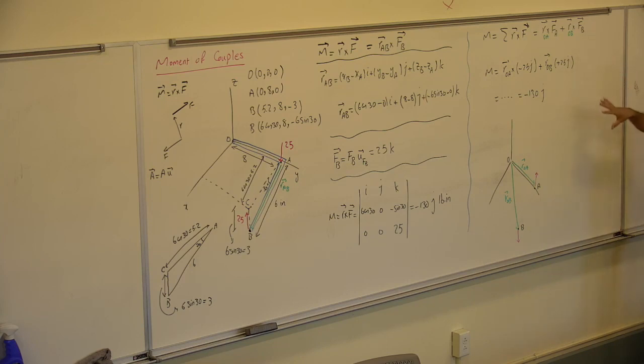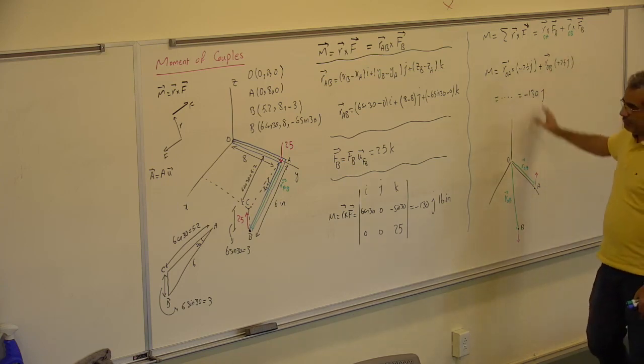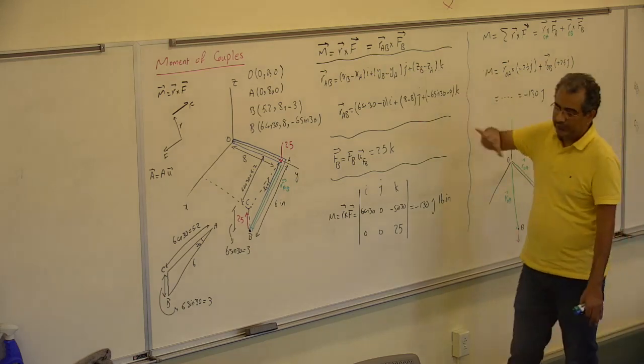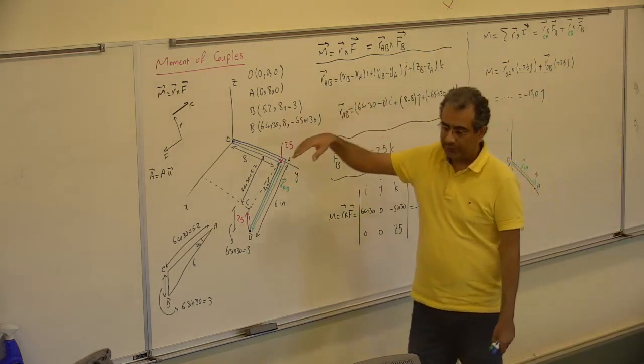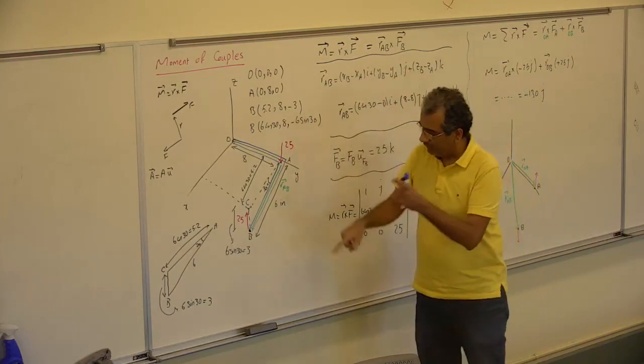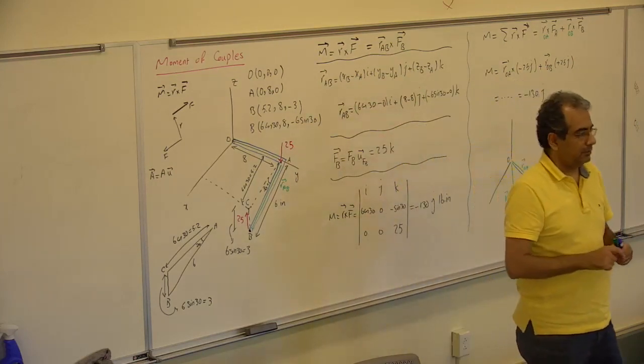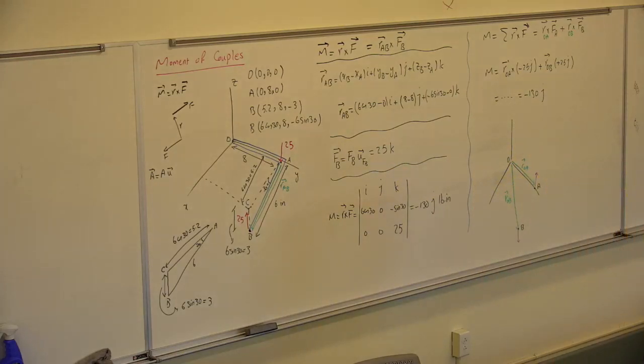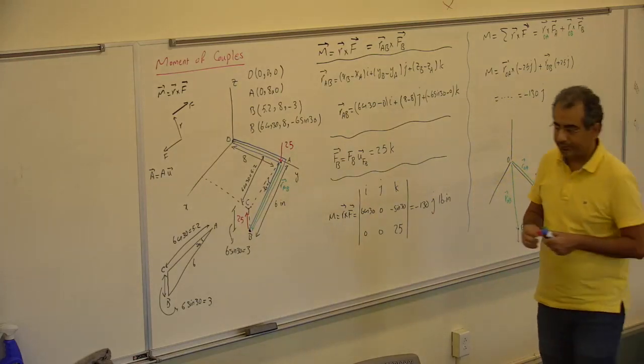So what it did here was calculate the moment for each of the forces separately and add them together. This is the first method the book did. The second method I used because the topic we're covering is that they are coupled, or equal and opposite in direction, so just use the couple formula to do the calculation.